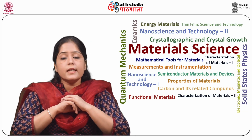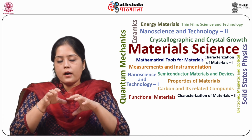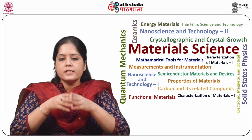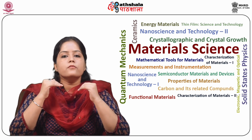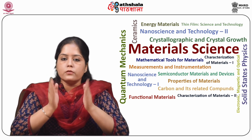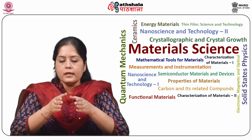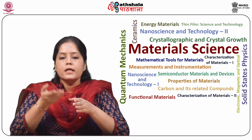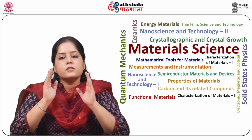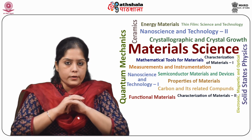Let us first discuss the interface trapped charge. QIT is due to the Si-SiO2 interface properties and lies in the forbidden gap. It depends upon the chemical composition of the interface. The interface trap density is orientation dependent. For example, in the 100 orientation it is smaller than in the 111 orientation by about an order of magnitude.